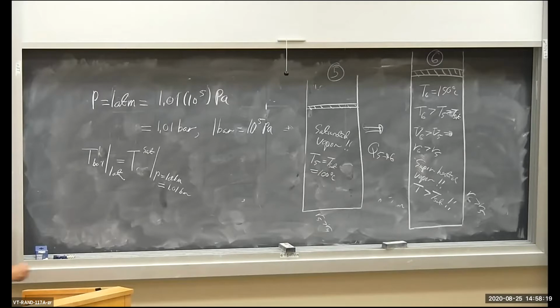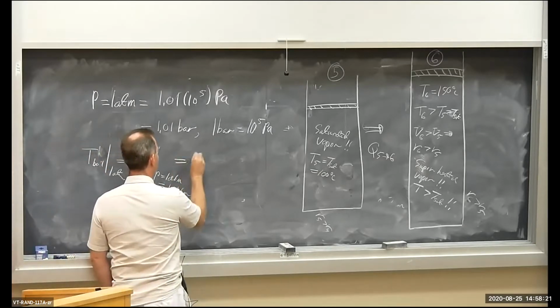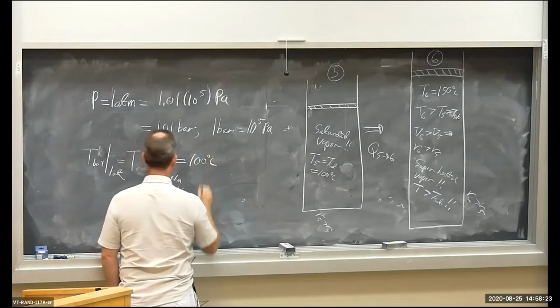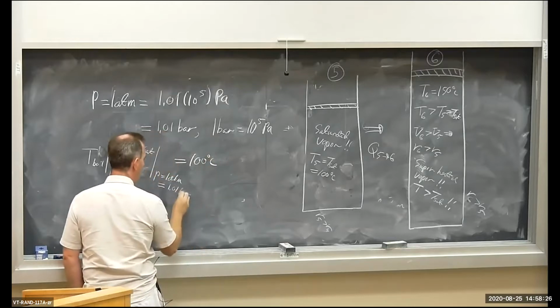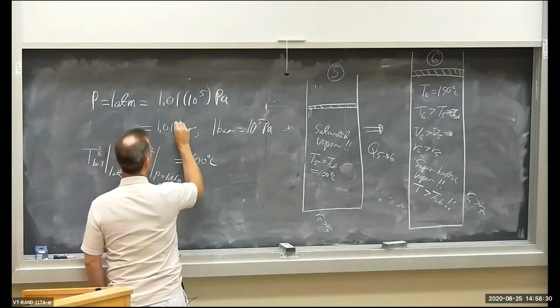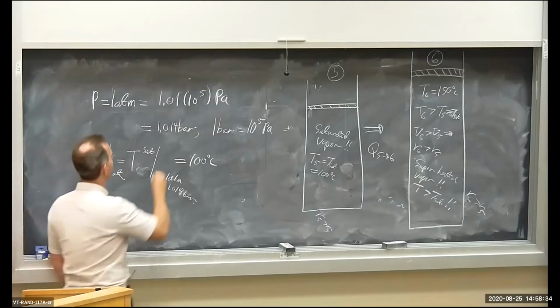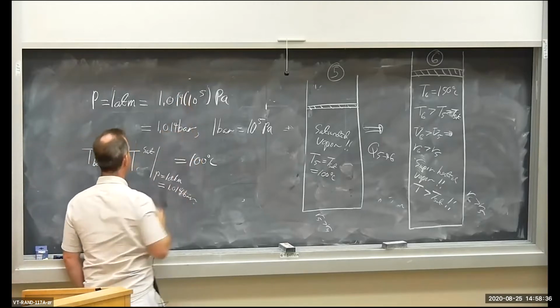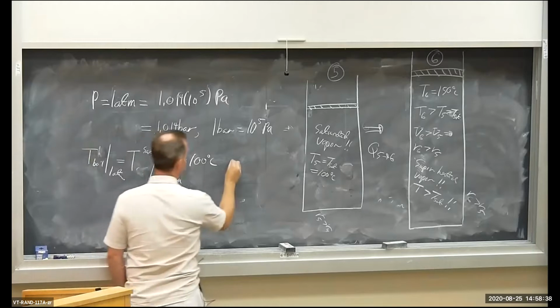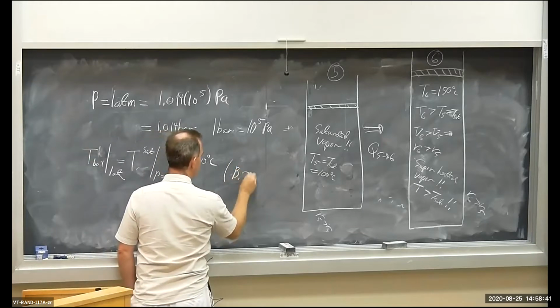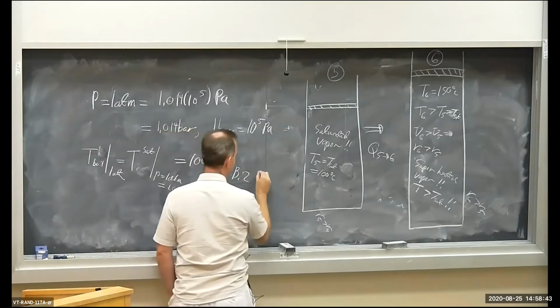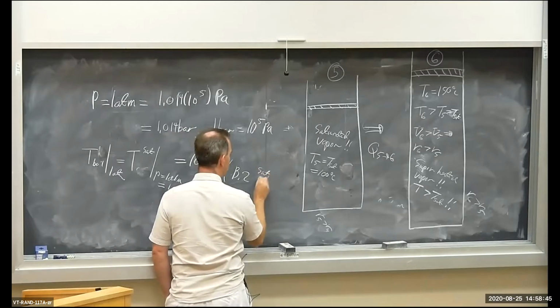So 100 degrees C. It's actually 1.014 bar, if you want to be precise. So I'm going to put a 4 here, 1.014 bar. I'll put the 4 here too, all right? And we got this from table B2, saturation tables.